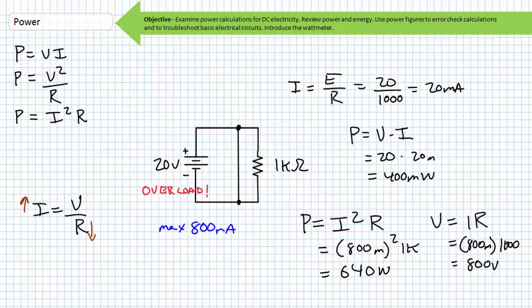If you took a voltage reading across this resistor, you'd not find 800 volts, nor even 20 volts, but rather a very, very small voltage because our power supply is current limited. Current is the effective voltage. If current is high because of low resistance, the power supply simply lowers its output voltage until it reaches that preset current maximum. Let's assume our short in parallel with our 1 kilo ohm resistor is not 0, but rather something very small, on the order of 1 ohm.